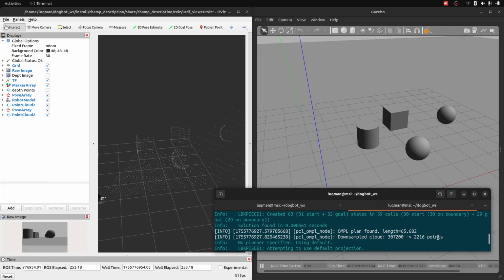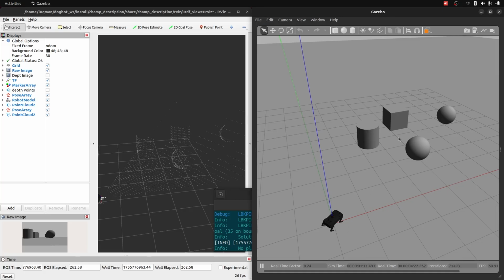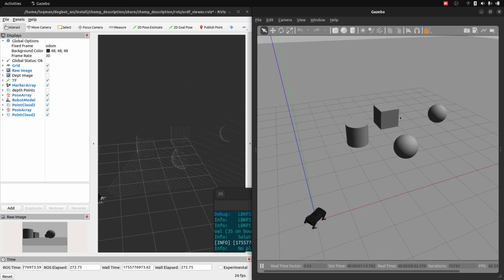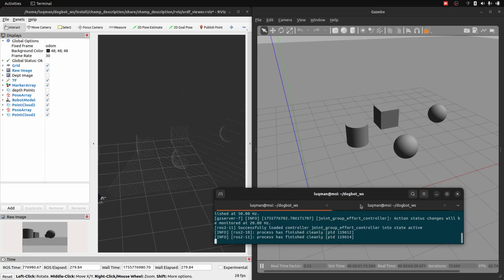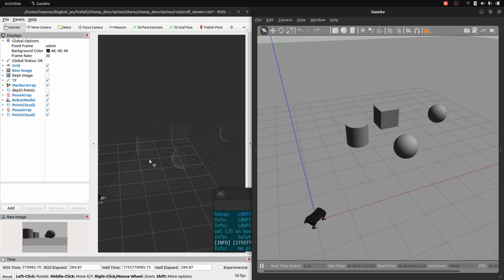But what is important is with these small points, we are still able to find the path, because OMPL found the path starting from the origin point, which is 0,0 to 5,5, which is 1, 2, 3, 4, somewhere here. It has been able to find the path, although there is an obstacle on it, but we have disabled obstacle avoiding and made it very simple for you. You can add more functionality to it. The main purpose of this whole process was to make you understand how to add libraries into basic scripts and ROS2, which has been achieved.